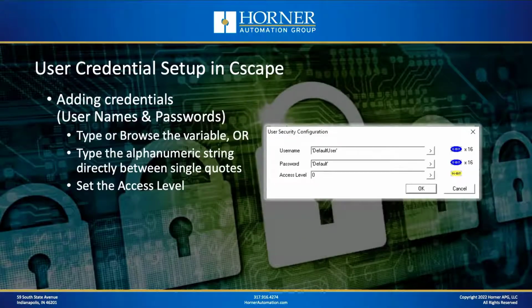So when you decide to go ahead and add those credentials or maybe edit some existing ones, it's really just a matter of pressing the appropriate button for edit or add, etc. And then I recommend hard coding in between single quotes the username and the password. When you first go to this original dialog for adding the credentials, you'll see that there is a default set of credentials called default user with a password of default. So I typically just leave this one in and then just add additional ones to it.